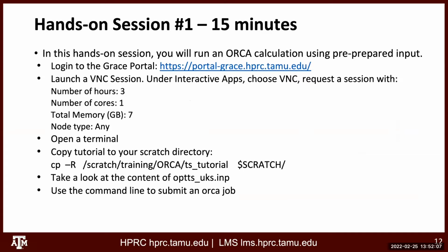All right, now here we come to our first hands-on part. In this hands-on part, I've already given you an input file for a guess of the transition state structure. You will be able to visualize that transition state structure and submit an ORCA job to the queuing system. So this time we're not going to run it interactively.